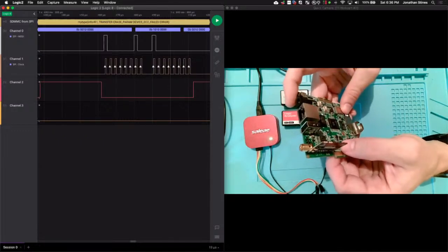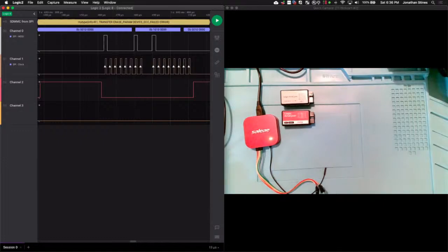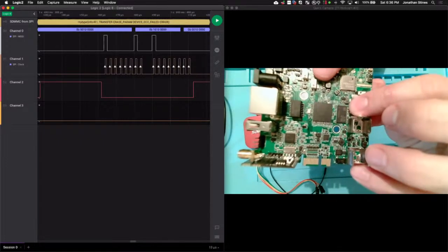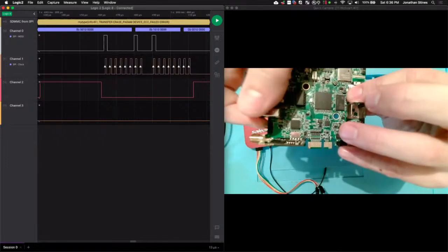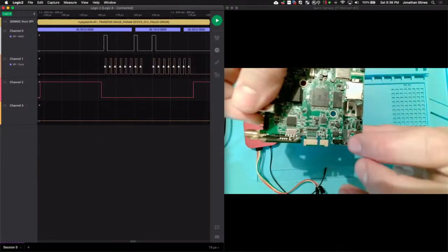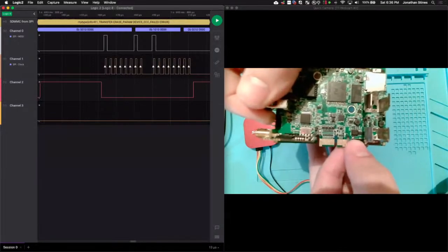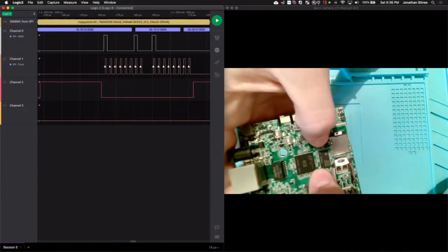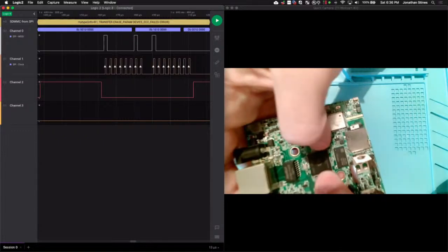And when I mentioned WSON earlier, actually I can't quite tell if this is WSON or actually a BGA, but either way, same difference. Sometimes you can't actually see the legs of the device to where you map it out to, like, for instance, these headers, but sometimes you can, which is what you see right here. This is a traditional TSOP 8. So TSOP 8 has the legs. WSON does not. I'm pretty sure it's WSON. It might be BGA, but I'm pretty confident that it's WSON. This one for sure is a BGA microcontroller.